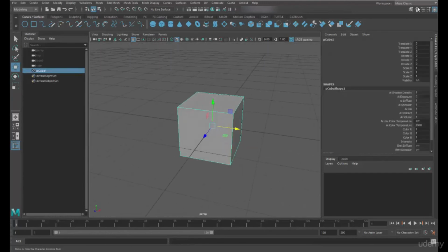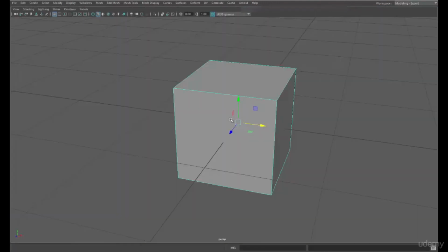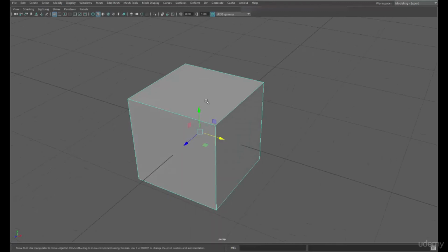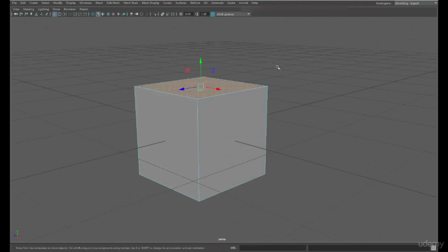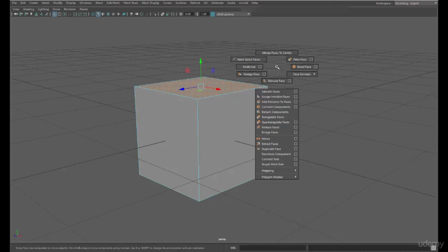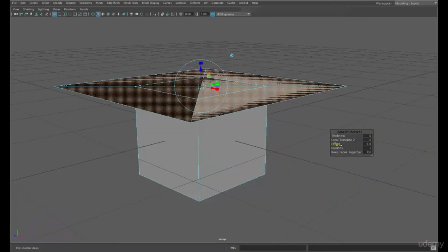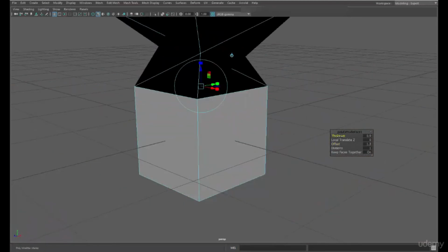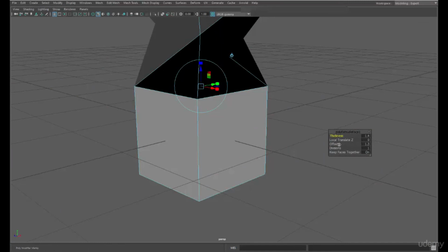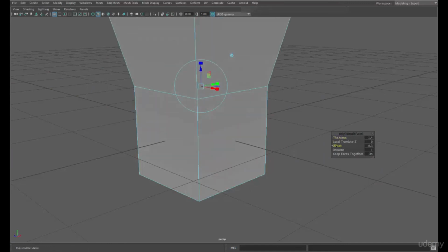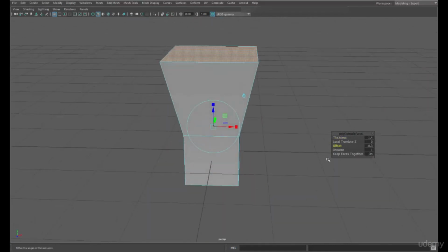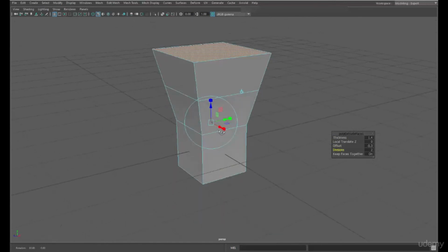And if we're modeling, if we're in the expert mode, let's go into expert mode and we're modeling, we might be selecting a face. We might then choose to use the shift key to extrude the face. We might then create an offset on that face. Let's just create a positive one, and a thickness. Let's just bring this in. We might put a division in there.